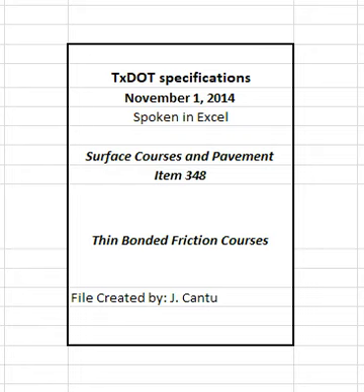Supply the engineer with a list of certified personnel and copies of their current certificates before beginning production and when personnel changes are made. Provide a mixture design developed and signed by a Level 2 certified specialist. Provide Level 1A certified specialists at the plant during production operations. Provide Level 1B certified specialists to conduct placement tests. Table 6. Test methods, test responsibility, and minimum certification levels.